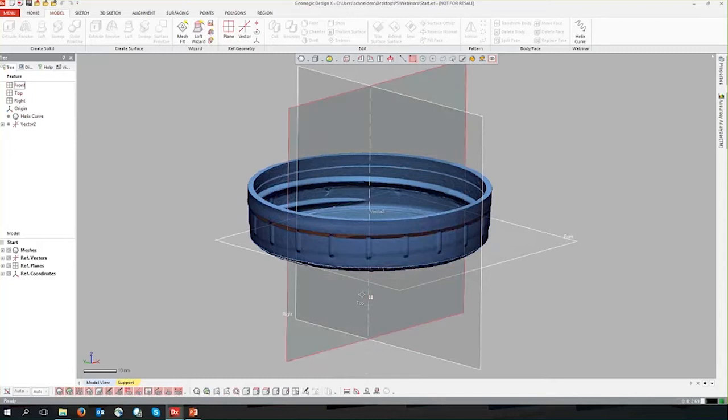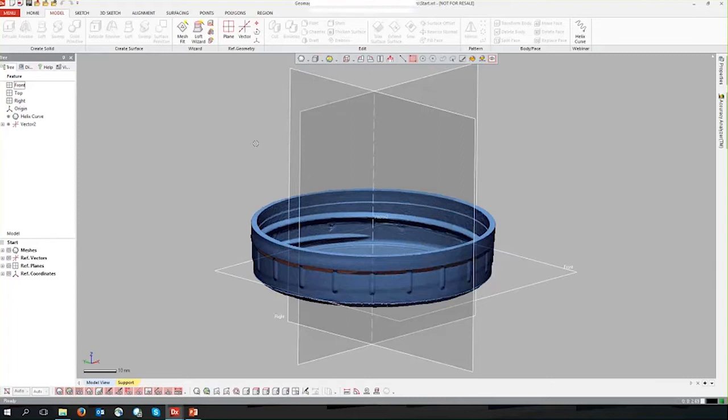There's one other thing we need to start our helix, and that's the starting point. The helix can have a reference point, just a reference geometry to start our point. But another trick to use this tool for is to actually get a sketch point to be your starting point. As parts wear and they're used, usually the geometry you're modeling isn't there. So instead of having to find a way to move a reference point from the scan itself to someplace in space, it's easy to just generate a 2D sketch and generate that point there.